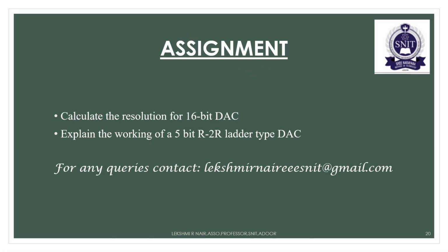The assignment questions from this portion I am giving is calculate the resolution for 16-bit DAC. This you can do with that equation 1 by 2 power n minus 1. In that case, substitute n is equal to 16.